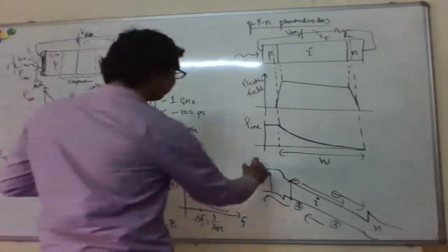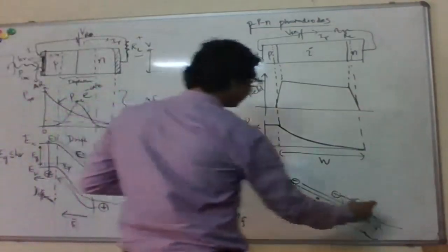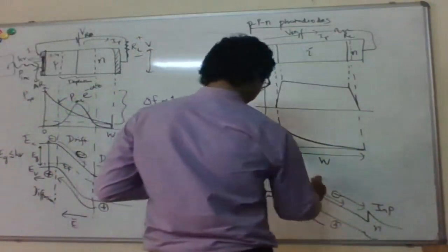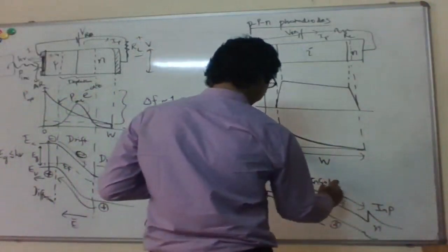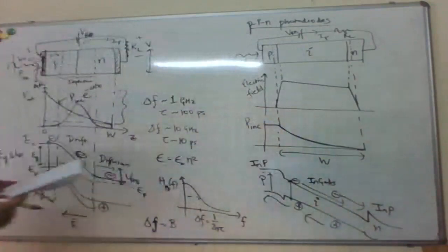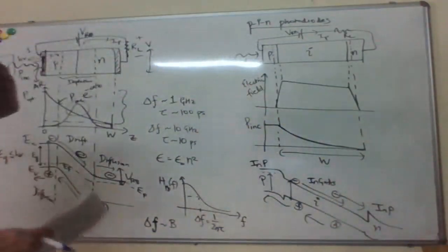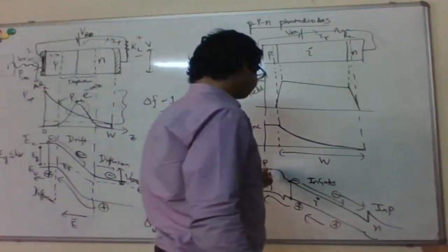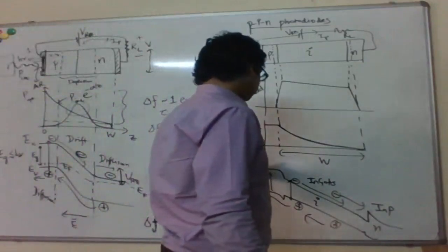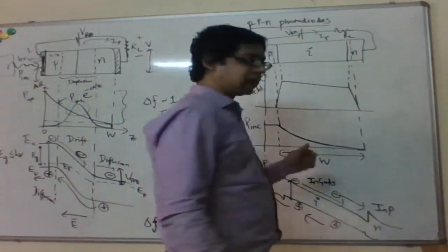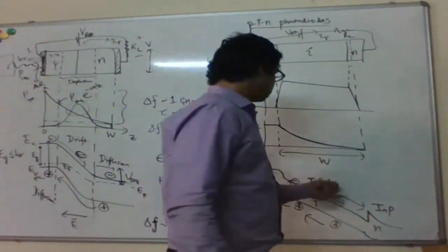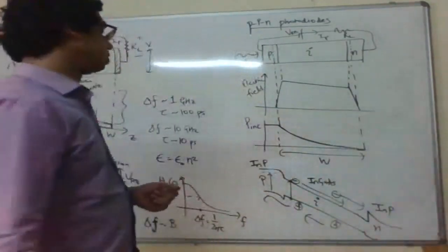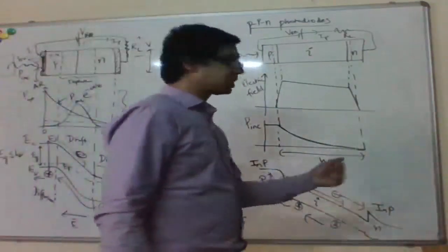Okay, so for example, you can have the P and N regions again, like indium phosphide, and this one like InGaAs. Right, so if you maintain this ratio of the mole fraction of the indium and gallium versus arsenic and phosphide at this 0.45, then you know that these are lattice matched.